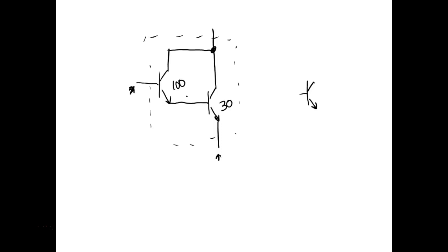Let's just take an amplifier down here. Say, okay, this thing gives me a gain of 5. So I put 1 volt in, I get 5 volts out. Now this guy right here has a gain of 5. I put 5 volts in, I get 25 volts out. So gains are multiplied, guys. They're not added, they're multiplied. So what would the gain be? This circuit would have a gain of